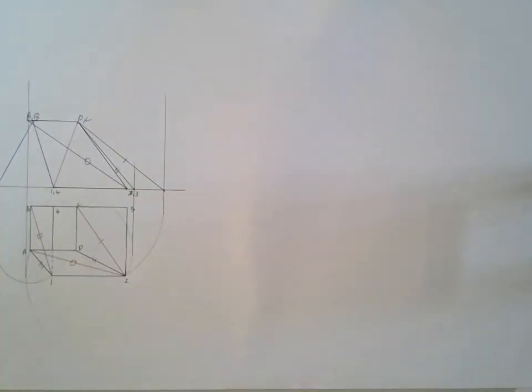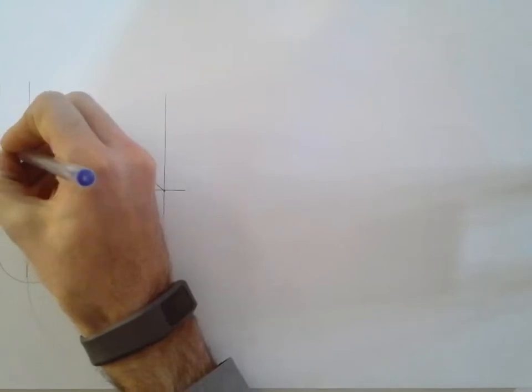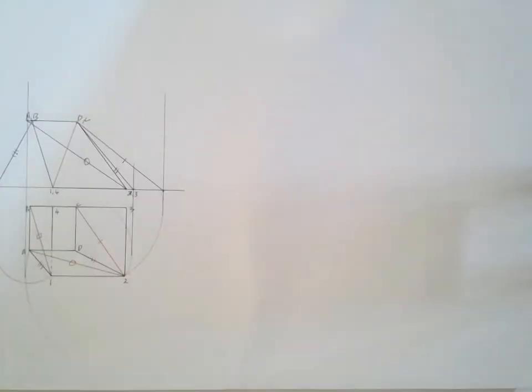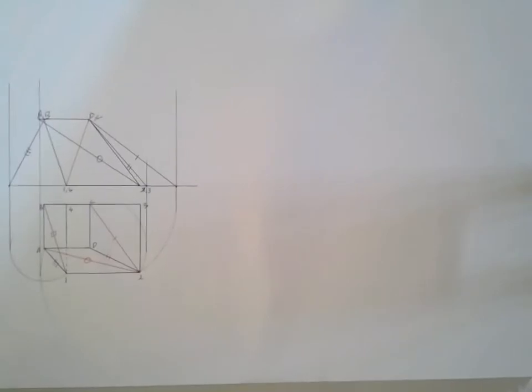Okay, so that line I'm now going to mark with 3 lines. So we've got that true length. Sorry guys, missed a little bit of that. There we go. Okay, mark that one with 3 lines. Now, the last line that I've got to go and find a true length for is going to be line B1, which I've marked with a square.